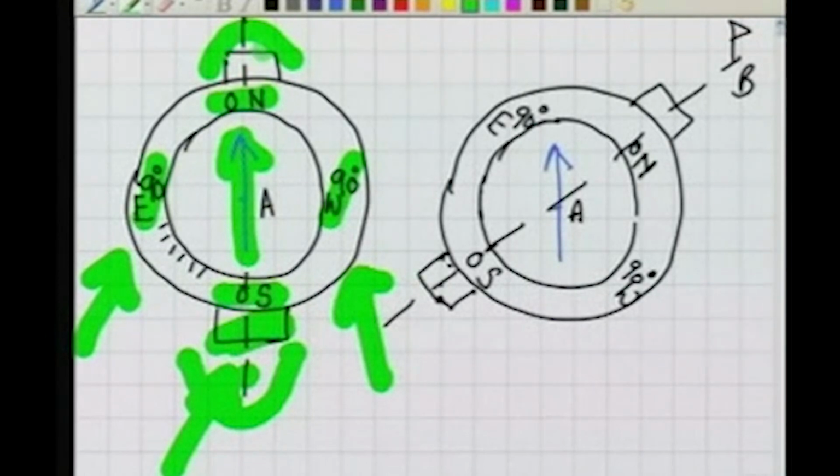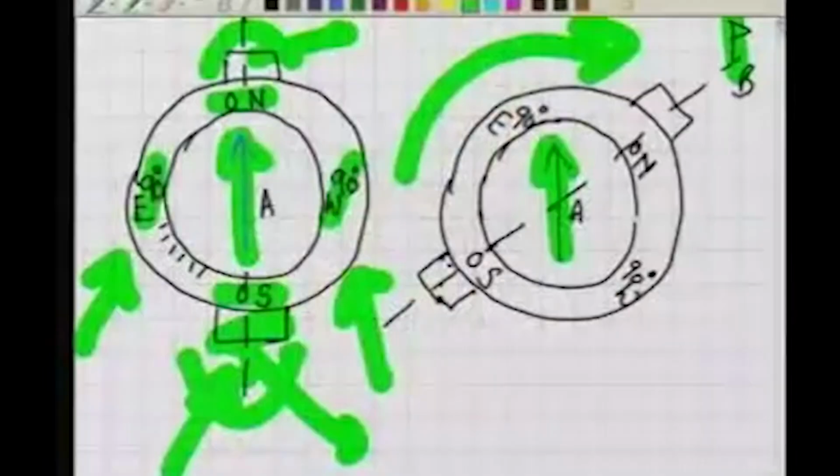So a wire here, a wire is here and a slit here. Now using this slit and the wire, we look in the direction of the object for which we want to measure the bearing. So in order to bisect B, we will have to rotate our instrument this way, while the needle will stay where it is. So the needle maintains its position.